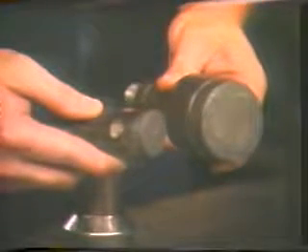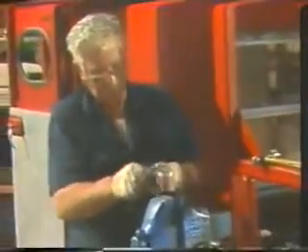It is an important tool to the wireline specialist when trying to identify tubing obstructions during fishing operations. It is made by pouring molten lead into a metal sleeve machined for this purpose. Once dressed to a smooth face, the tool is lowered to the obstruction and gently set down on it. Jarring down only once will give an impression of the object to be fished.